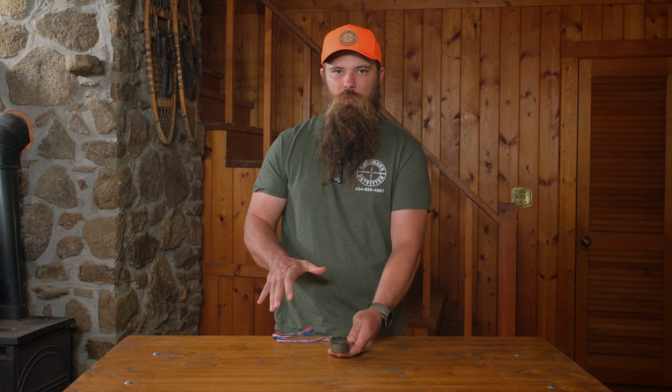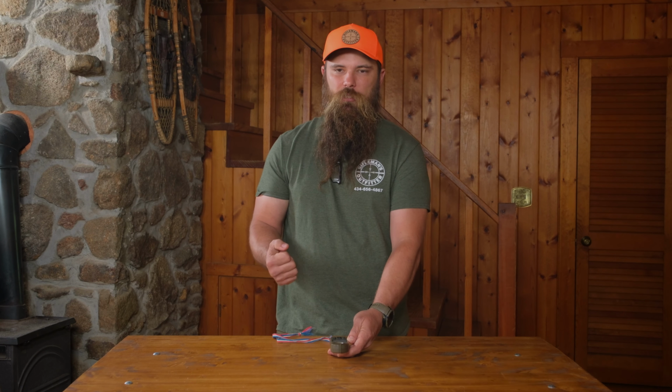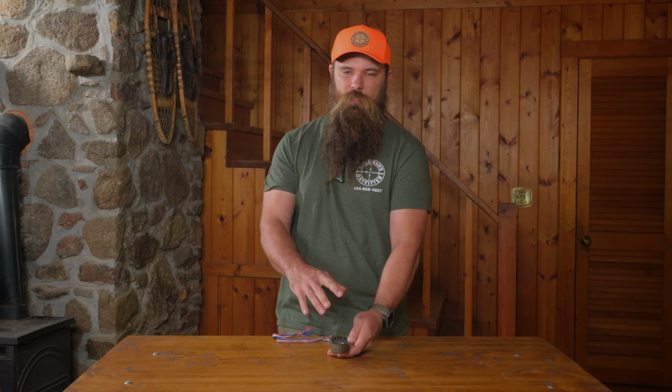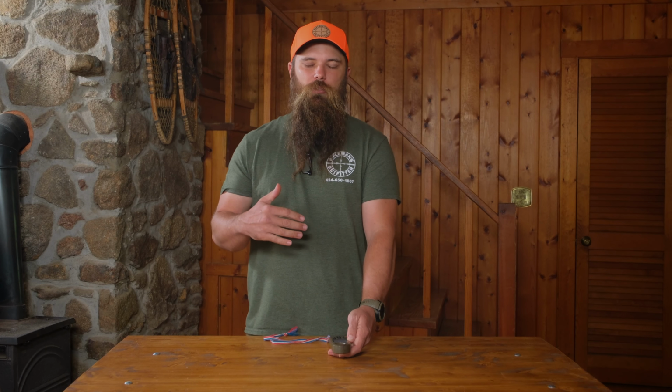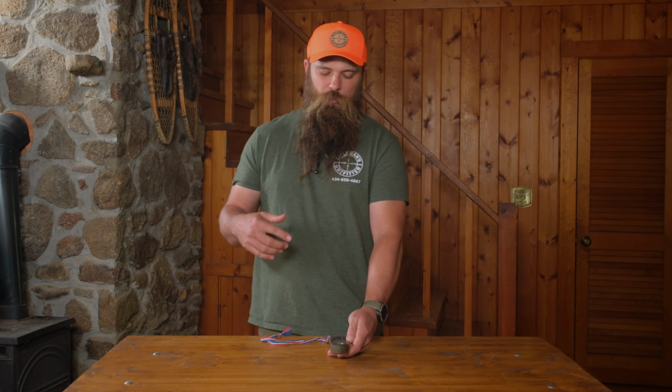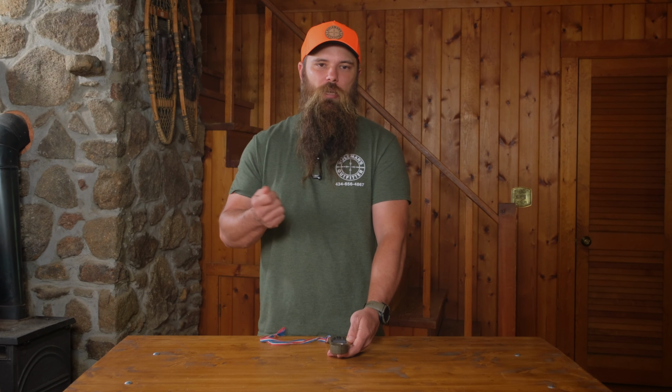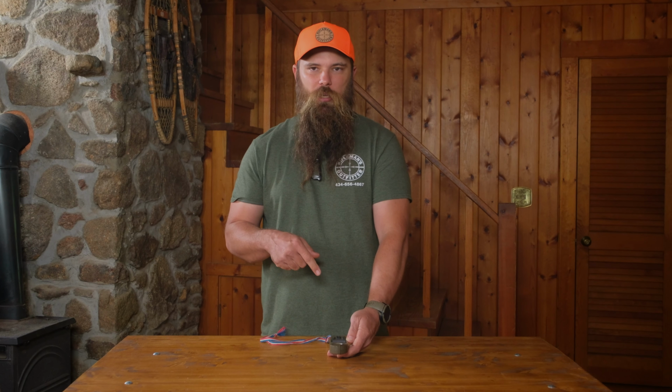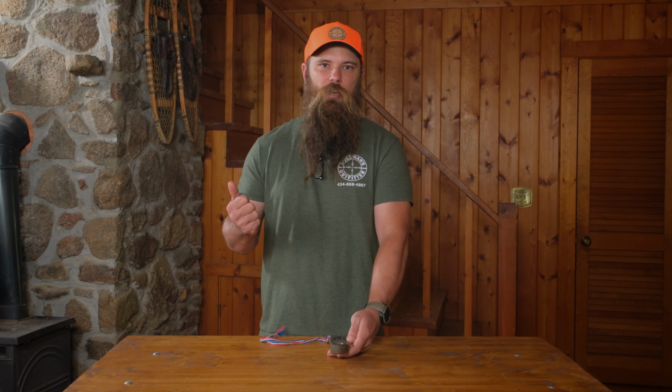The reason I run it on lock is because of your hand temperature, if you keep it in your pocket, or if it's out on a sunny day and the hot sun is heating this thing up, you don't want it to get heat soaked or cold or whatever. We want it acclimated to current ambient temperatures. So if we are using it for that current condition, we'll spin it, get that current ambient condition, and then we'll lock it so that it's not sucking heat out of our hand or building up heat from the sun.